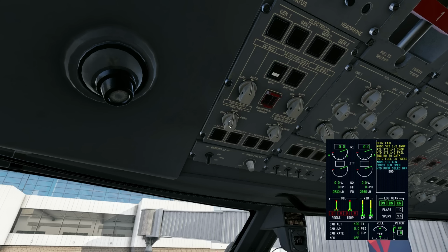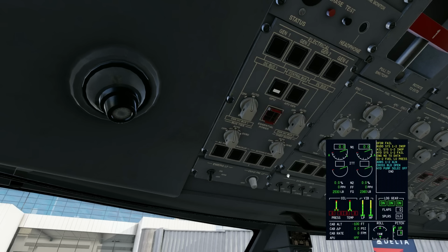The bus ties controller is how we can interact with the electrical logic. There are pages and pages in the manual on different configurations of all the bus ties, depending on the type of electrical power available. It's all controlled by the computer, but in certain failures, there are procedures that require you to hardwire things, override, so basically all of the bus ties are energized, or turn them off. Again, this will be driven by a procedure when the electrical logic has failed. In normal operations, we never touch this, but it is there in case you need it.